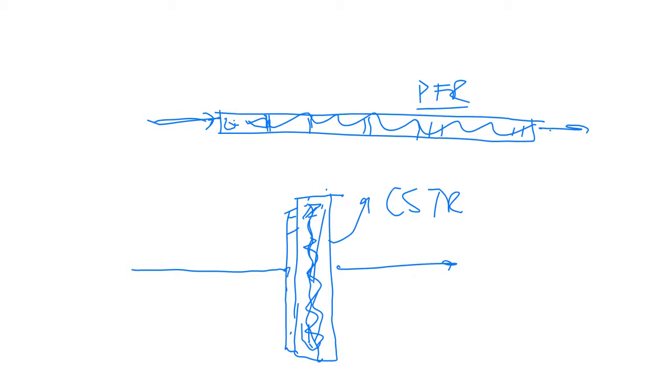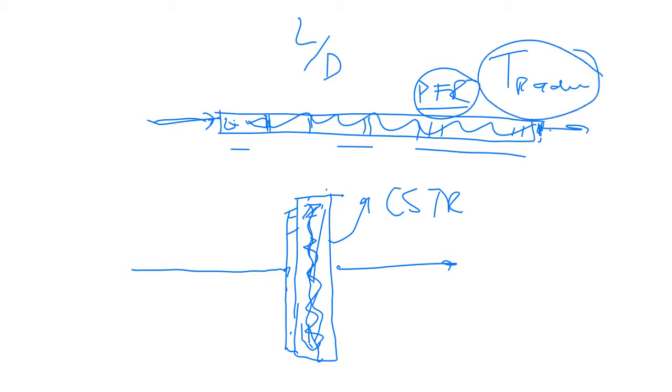So this is one of the other aspects why it's important to have a decent L over D value, length over the diameter value, for your reactor, to ensure plug flow, to ensure that I don't have any radial temperature differences. Okay, let's see if you are satisfied with my answer, Camille? That's the downsides to increasing the tube size in a nutshell. Well, not a nutshell, I probably talk too much.